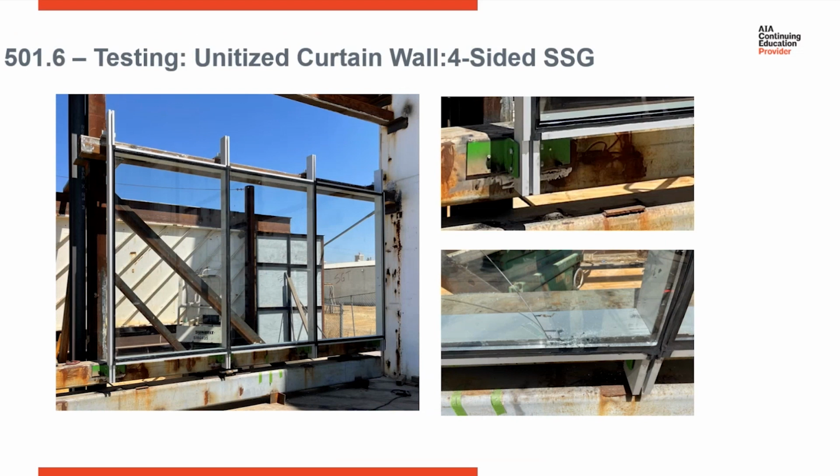Again, this is some of the aftermath from testing that unitized system. It was an SSG system. So this is one of those cases where it's very hard to use that calculation for it. It's preferred to just do the testing. And you can see in the bottom right corner here, there was some glass cracking, but there was no glass fallout during this test.